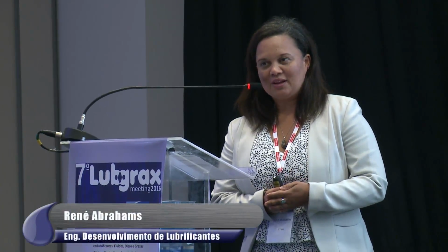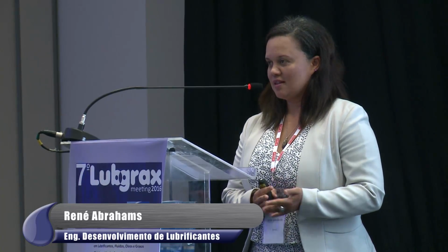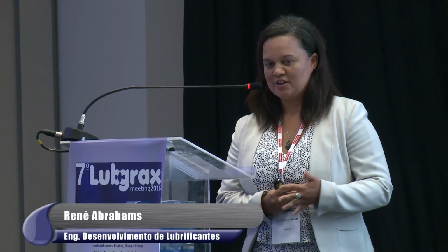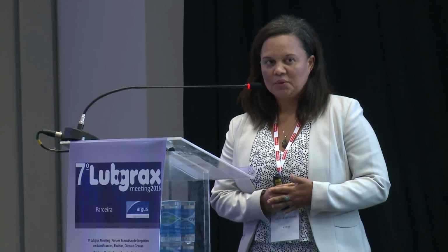So they took these 2 samples. We made some greases. We use a simple lithium conventional grease and 12-hydroxystearic acid. We use the same base oil throughout the production process. We targeted an NLGI grade 2, and these were just base greases without any additives.